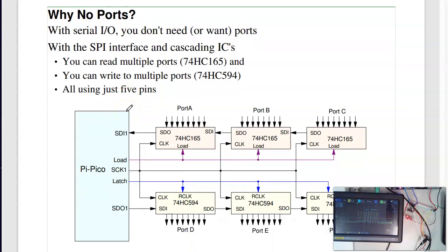This is one of the reasons the Raspberry Pis do not include ports. The microchip that we used in 376 had port A, port B, port C, port D, port E, the different ports. When I write to a port, I write 8 bits. They don't do that with the Raspberry Pi. The reason being that, again, the I/O pins have other functions. Doing parallel input like that really uses up a lot of pins. The Raspberry Pi is really designed for serial I/O.